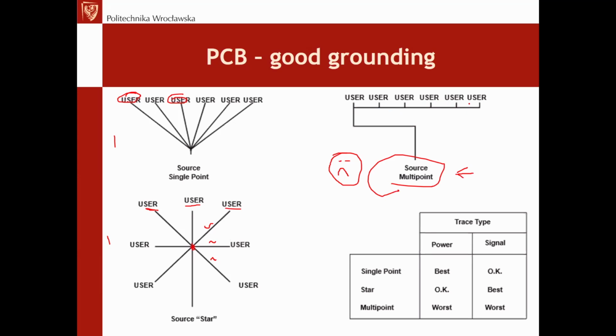Why? Because take a look. It works this way. Each line has a certain impedance, in the DC scale, but even worse, the impedance for high frequency circuitry. As we mentioned, a simple via at 2.4 gigahertz is 18 ohm. And with this technique, there is current flowing on the ground plane.